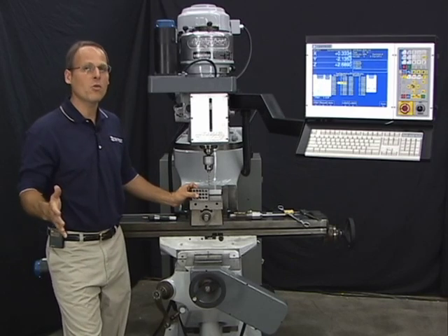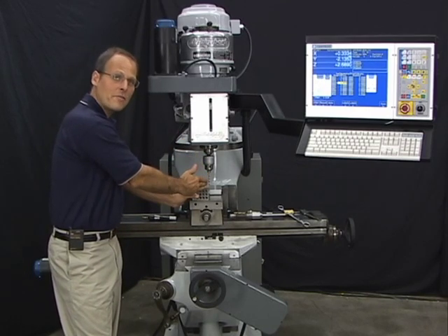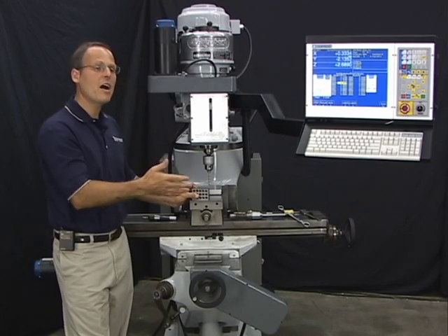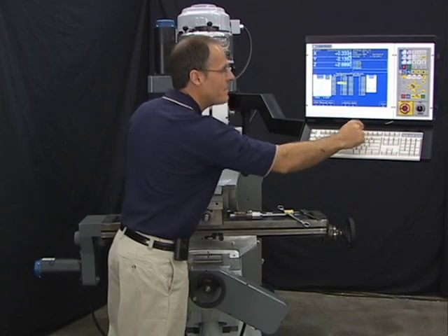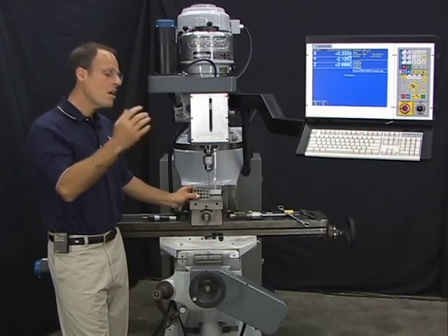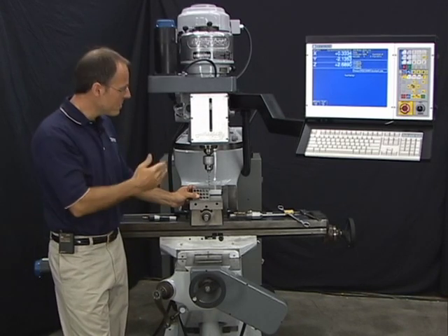Now, if I had 25 more tools, I would just continue on in the same method, touching off the top of the reference position here, measuring the height offset value for each individual tool, and be sure to hit F10 to save the work that you've done. Now I've got these 3 tools in there set. I'm ready to go program and set my part zeros and cut my job.